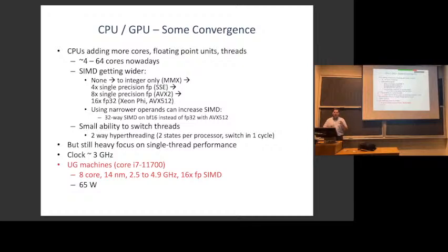So it's looking and seeing what's ready to go, sending them to the execution units, and they're all tagged so that they don't start writing over each other's registers and so on. This typically gets maybe 1.5x the throughput. It's not as good as having 2 cores because you're still sharing the same execution units. But depending on exactly what the threads are doing, it's pretty common that you can get maybe 50% more throughput. And the hardware they had to add to do this wasn't that much. So it's a pretty good trade-off if you've got lots of threads. If you don't have lots of threads, then it's wasted, but it's not that much hardware.